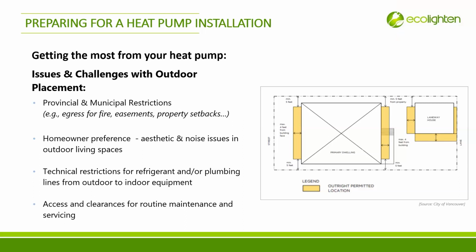So we are wondering about putting an indoor coil that is quite far away. Do you have to do a reverse inverted trap so you don't get liquid slugging coming back to your compressor? It's not recommended. Yeah, it's not recommended to do that. First thing is to make sure that you're within the maximum line length from the manufacturer, right? Often on a typical city lot, that's easy to do.